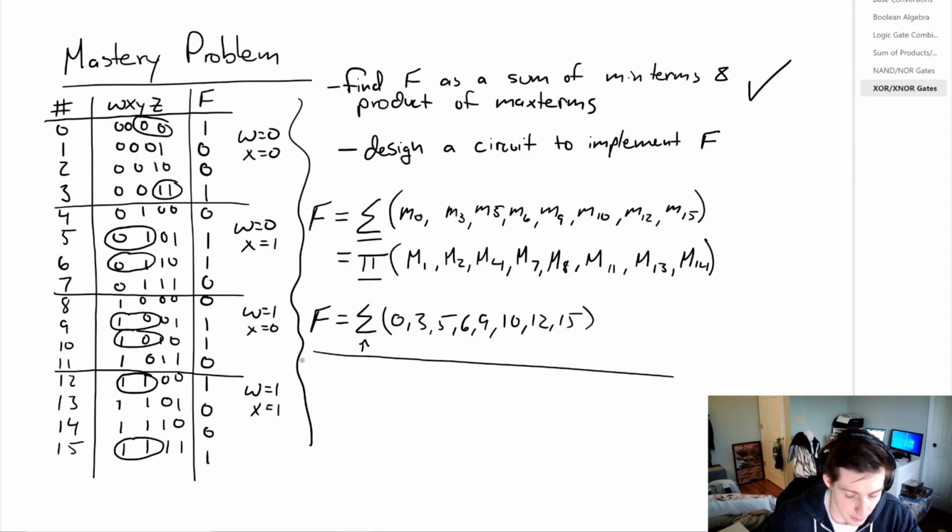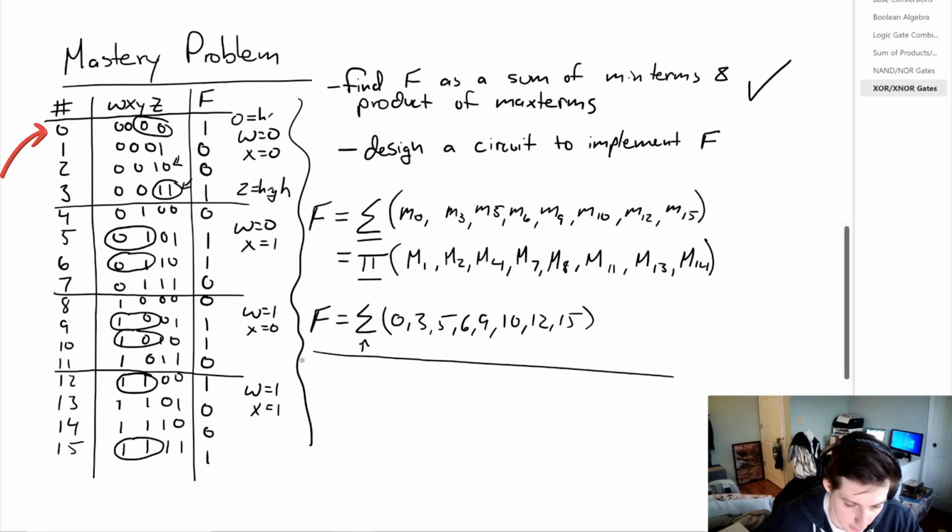And this is where you might start drawing a blank as to how to simplify this circuit and what's the catch. Well, maybe it's not anything special with Y or Z. Maybe it's something special about everything together. So let's consider all of the inputs. And for this last combination, you have 2 inputs that are high. Okay, but then here we have 0 inputs that are high. So if we go down to the second block, we start to see that if we have 2 inputs here or 2 inputs here, then we have a high signal.